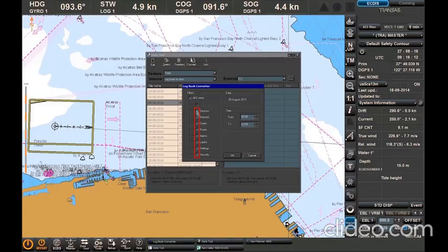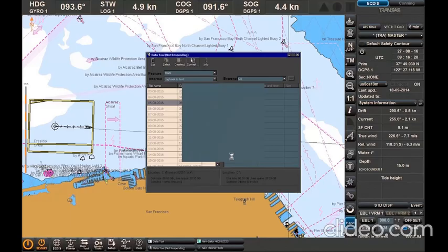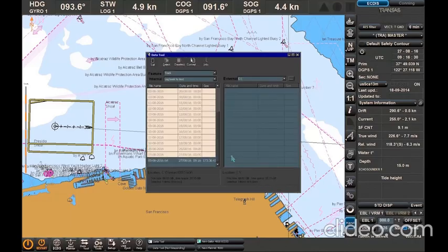Click the checkboxes in the Filters group to display the required groups of events. In the Time group, set the time interval for converting the log data. Click OK to confirm the settings. The converted file will be added to the general file list with the same name plus extension .text. The converting process is complete.